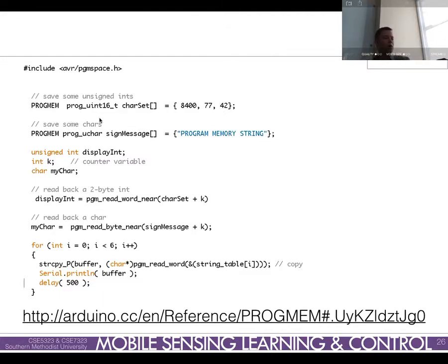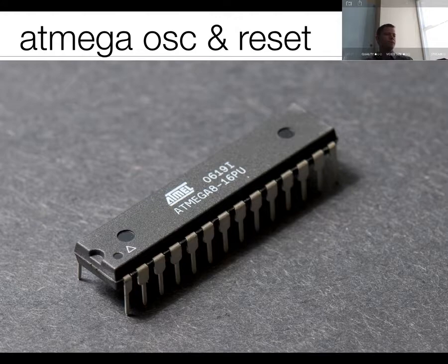Okay? Because you can't write to a location in program memory except when you compile the code. When you compile the code, it's going to write all of this into Flash, but you can read from it when it's running, right? Okay? Does that make sense? You can only write to it during compile time, whenever you upload the sketch, right? Okay. How are we doing?